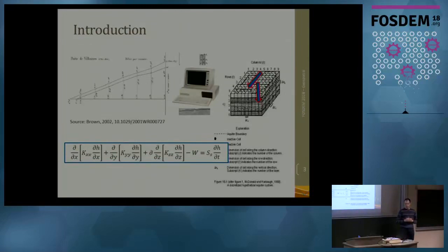For this, there are several options, but I think the most well-known package today, ModFlow, discretizes the subsoil in blocks, and then this equation in 3 dimensions is solved for each block. Solving this equation is not very straightforward, but there are a lot of tips and tricks, and there are solvers available today that are also open source.